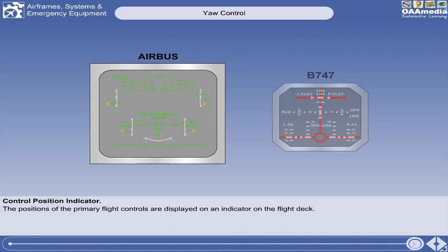Okay, so on the Airbus, in regard to the Electronic Centralized Aircraft Monitoring or the ECAM, there you will see the indications regarding your flight controls. Okay? So you can see there the spoilers or the speed brakes in particular, and our ailerons, the level of their deflection, whether fully deflected or not. As you can see, our right aileron is deflected upward, and our left aileron is deflected downward, because, right, they are opposite in direction.